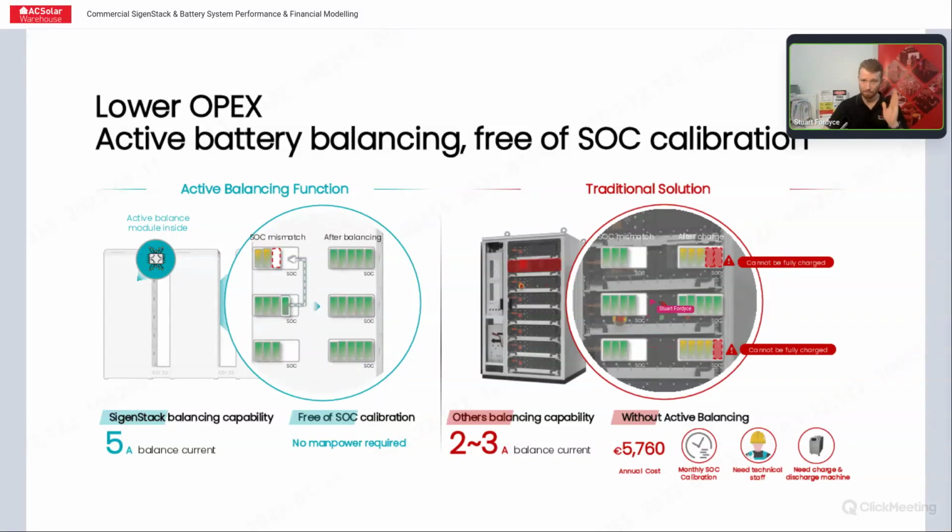it can register that entire stack at a 1% state of charge and stop it from discharging. And that means that you'll have energy capacity of that stack that's unusable. And without active balancing, more and more of that stack becomes unusable with time because of that effect.